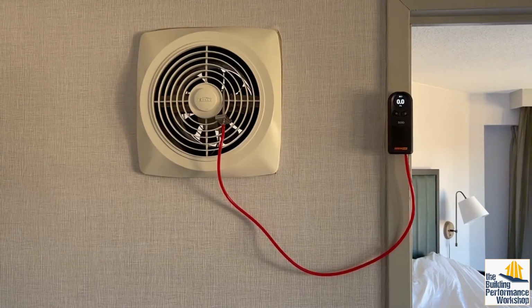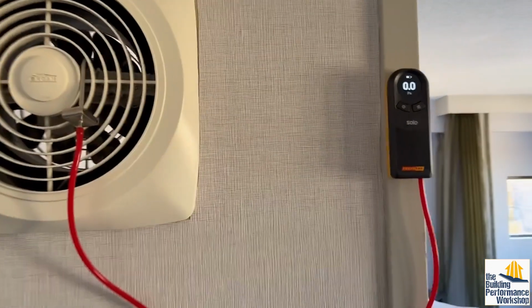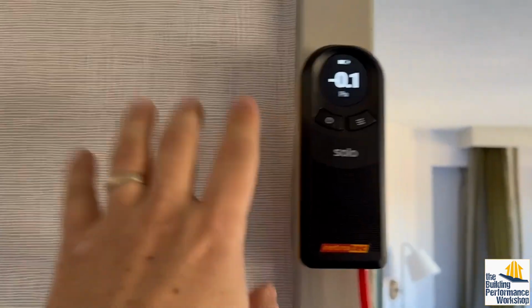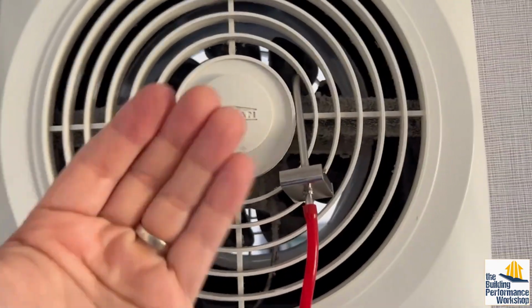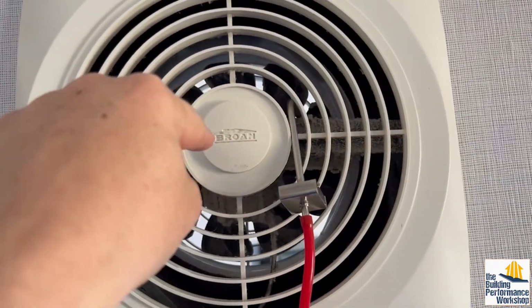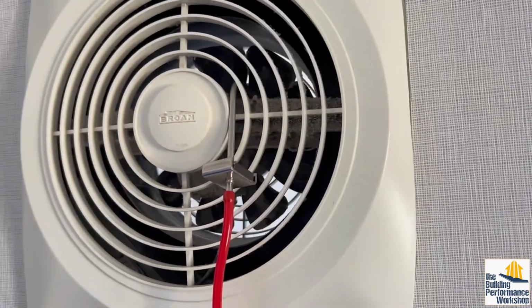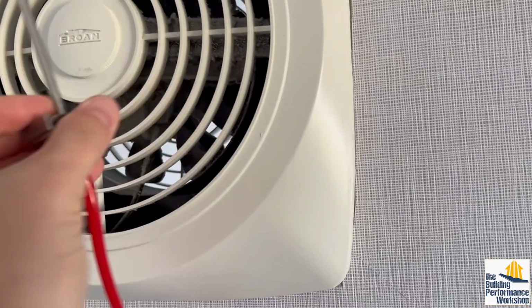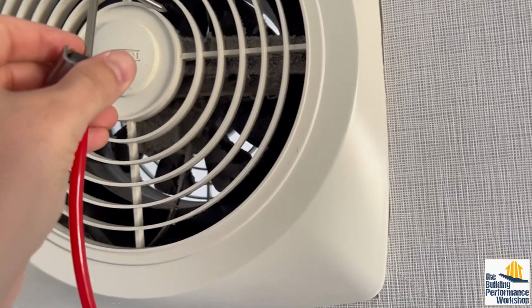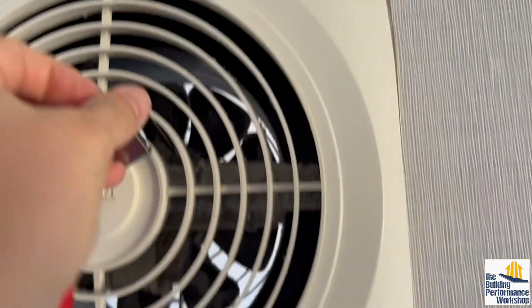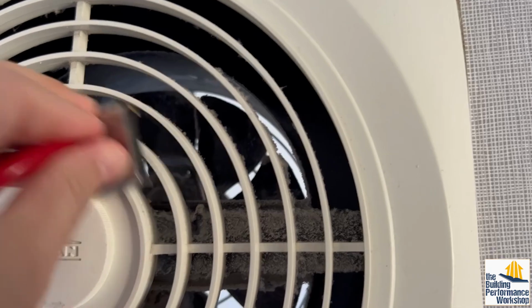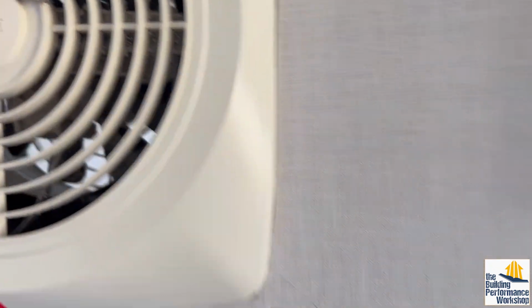So the way that I want to test this is with a hole of known size test. So this is basically an exhaust fan, right? So this is the exhaust side of it. The air is moving through that way into the bedroom. And what we can use is this static pressure probe. This is just to keep directionality out of the equation. And I know for a fact that this thing can't reach the fan blades. So always check that. Don't do this at home, kids.